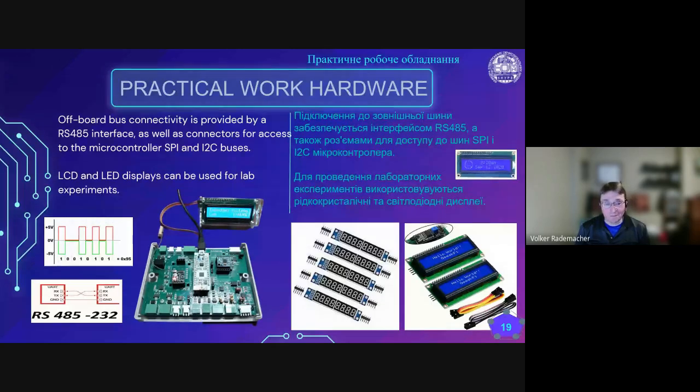Well, the typical Cat5 Ethernet is normally limited to 100 meters. Of course, if you use fiber optics or anything like that, then Ethernet is unlimited. But in an industrial context, it is usually easier to just use a Cat3 cable and RS-485.